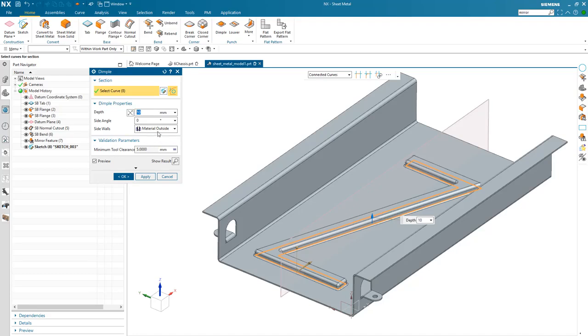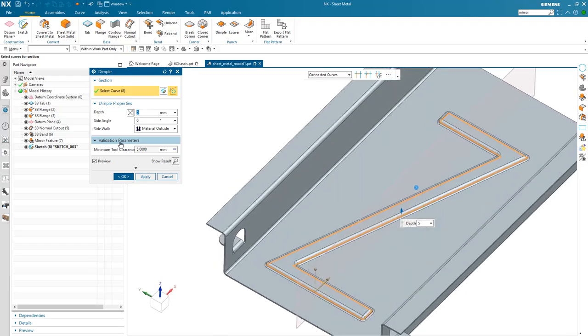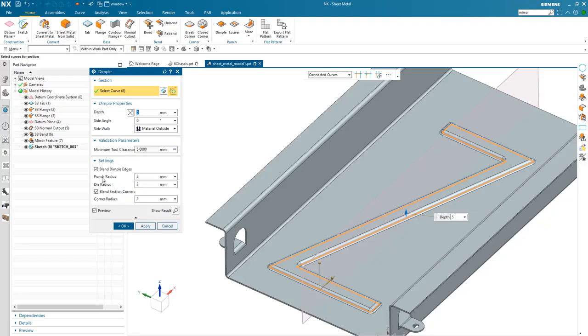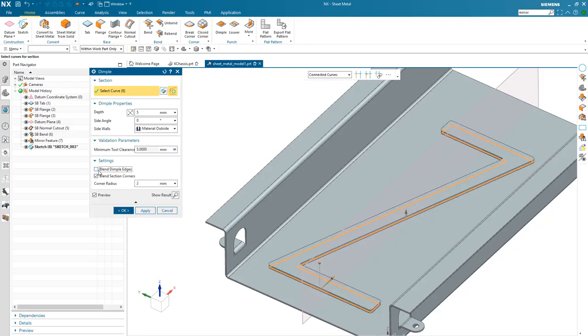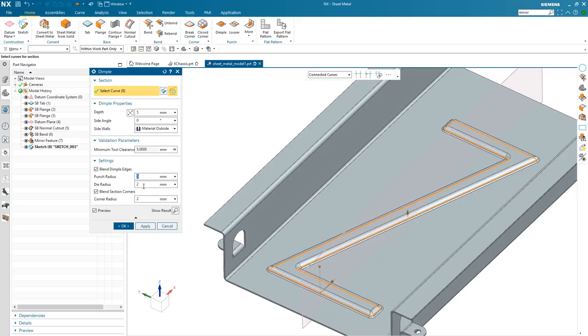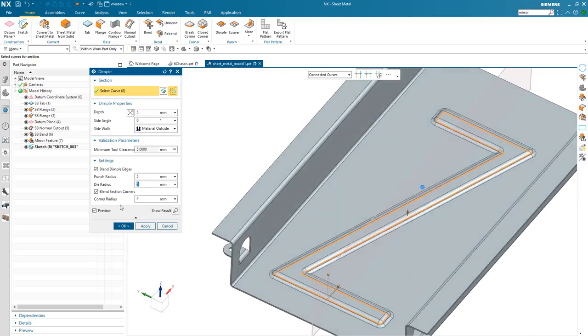And then as we select a value to make this punch make more sense, we can also soften up some of these so the transition looks a little easier. As the material is being stretched, we can also expand our selection intent to get more options, so we have more. We can increase our punch radius, all that kind of stuff. What that does is help define the tool better, how the tool is being utilized, and create a nicer, better transition of this particular dimple.